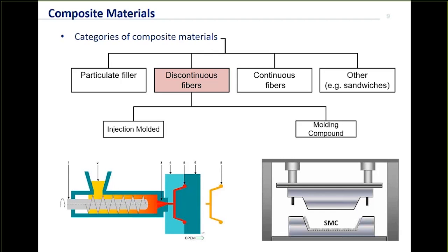Well, these types of material are typically made into shapes via a hot pressing operation, which shapes and cures it. So these types of discontinuous fibre material are very flexible in terms of the shapes you can produce, and not too expensive, but because the fibres are cut and not necessarily well aligned with the loading directions, you don't realise the full strength and durability potential of the fibre matrix combination.